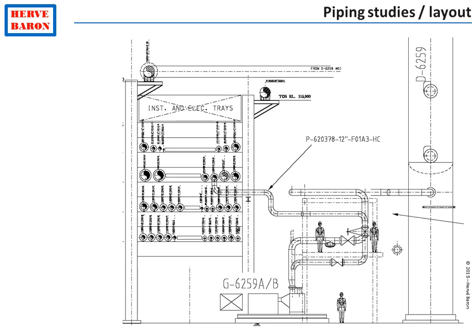Although these will be checked in detail by the piping calculation group, at the stage of piping studies, a flexible layout must be proposed by the piping designer based on experience. It will later on, as I said, be confirmed by calculation, but space must be allocated and adequate expansion loops, as the one shown here, for example, for the line connecting the bottom of the column to the pump, must be provided.